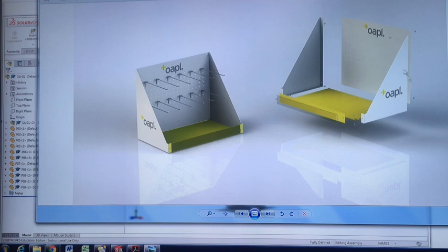So you might have done the exploded view in the assembly file, brought it into this larger assembly, so you've got one of each part, or one of each assembly, sorry, and then do a new exploded view, select this, and press reuse subassembly exploded view, and it'll just re-explode it in that file for you.